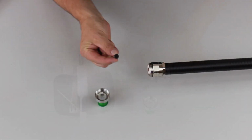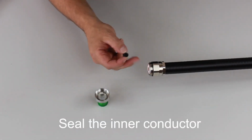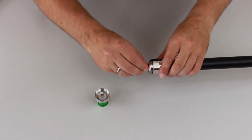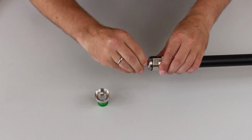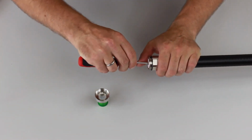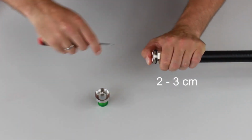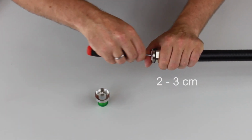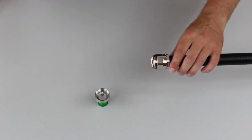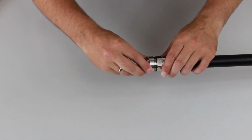To prevent dirt or metal particles located on the cable from falling back into the connector when you move the cable, seal the inner conductor with a rubber plug. Insert the plug and push it backwards about 2 to 3 centimeters. Then carry out a final cleaning process with compressed air.